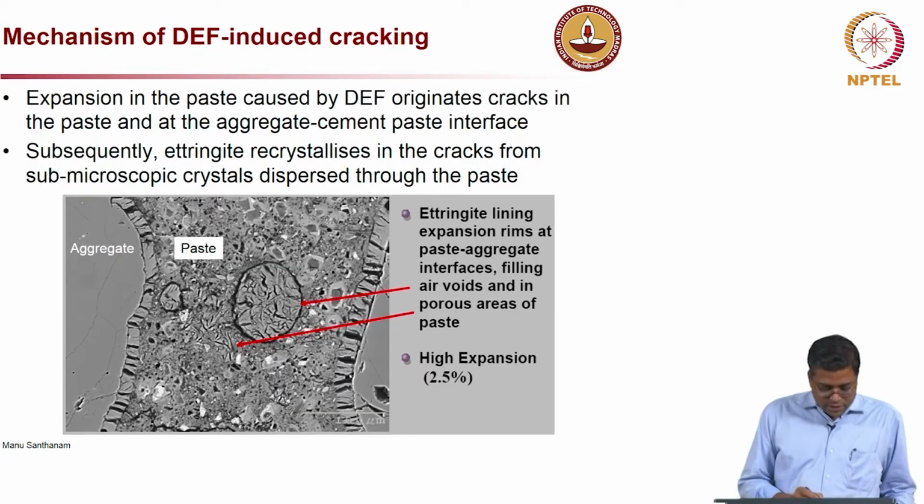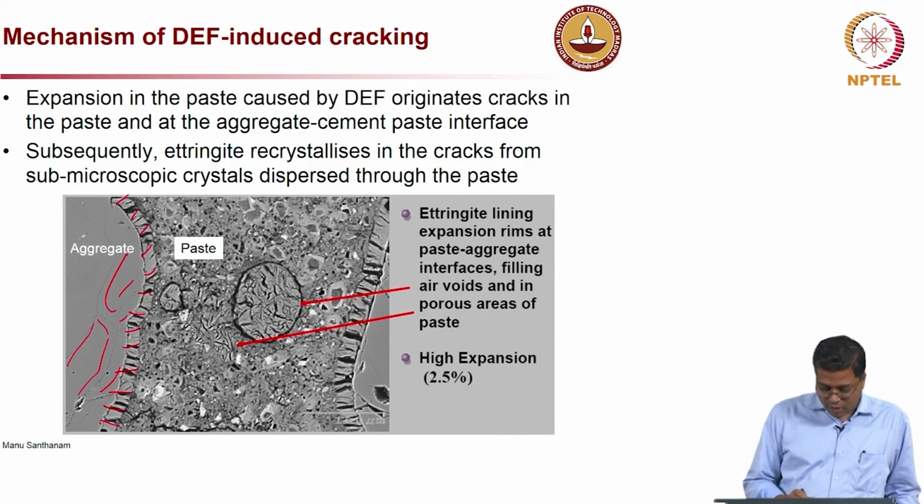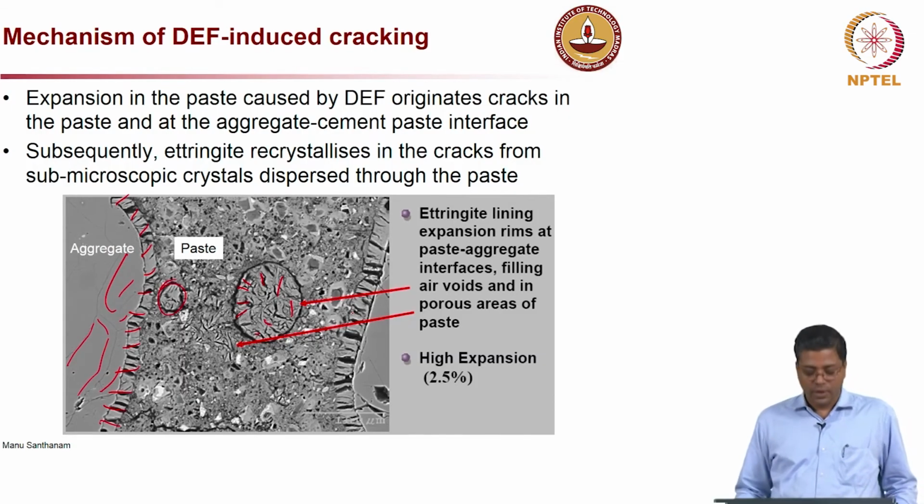Now, this we already discussed. You can see significant cracking here in the aggregate faces also, and these are all the needle shaped ettringite which are occupying the voids available within the concrete system.